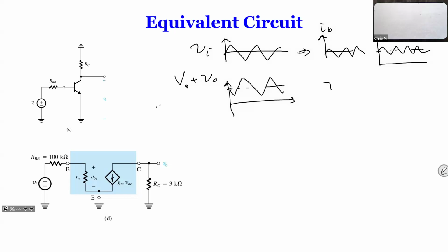If you draw the small vo only, this is going to be like this. So that's what it really tells you, how the waveform looks at each point. Just look carefully at the flip of the output in terms of phase from the input. The input is positive, the output is negative. The input is negative, the output is positive. So that's the only difference at that point.